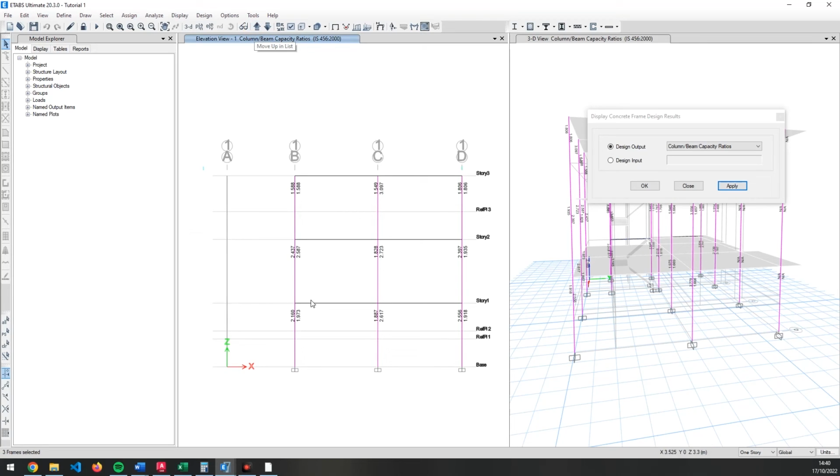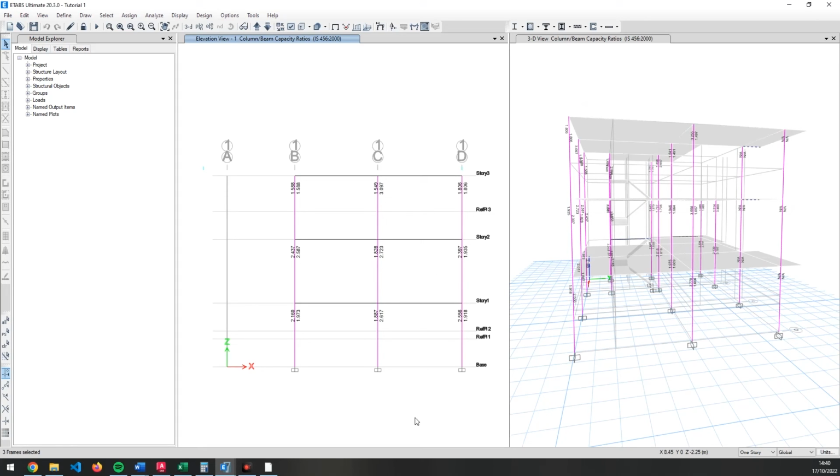This is because we haven't set the property for this cantilever beam. We have designed this cantilever beam as null frame, so that's why it is giving us the value not applicable. If you change the property to the concrete beam size, then some value will pop out here. So let's click on OK, and in this way you can design the equivalent static for the structural residential building.